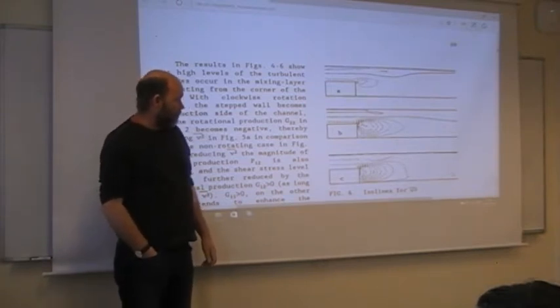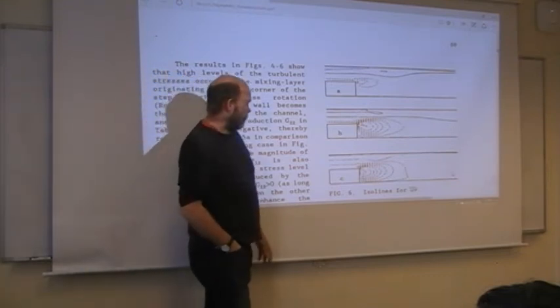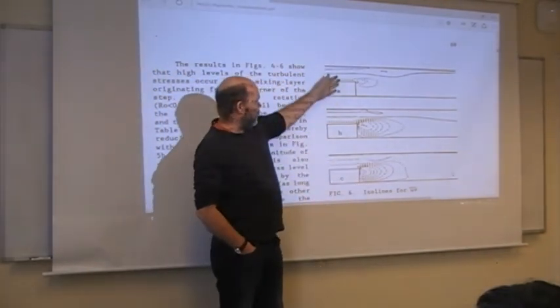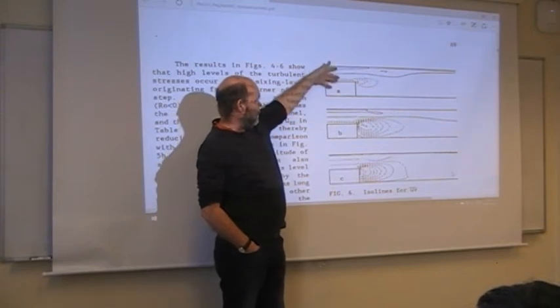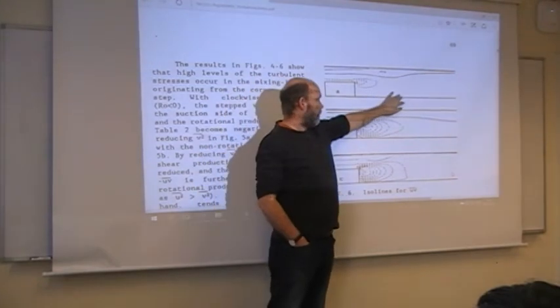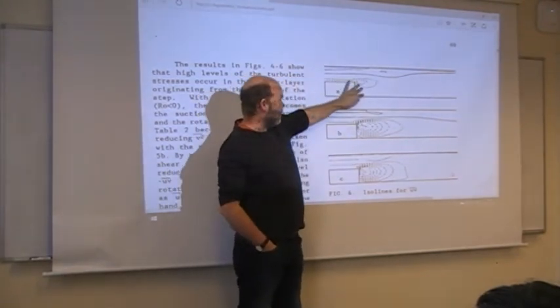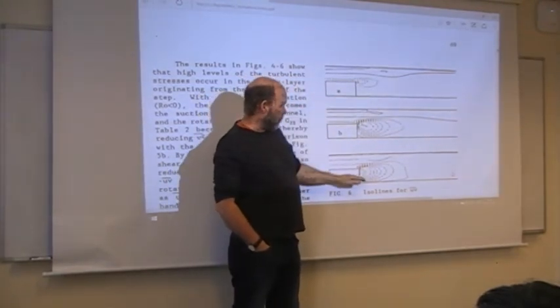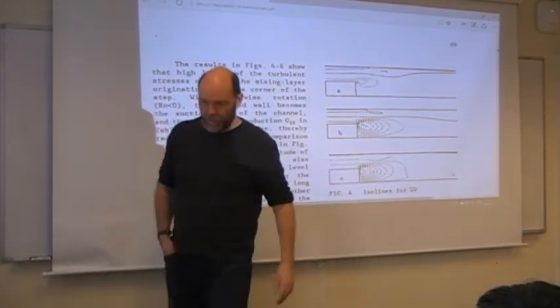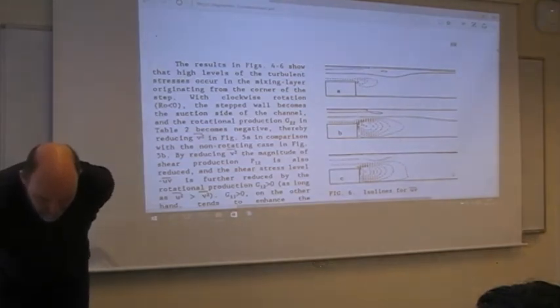The Reynolds shear stress, u-fluct v-fluct. Clearly some differences here, yes. The negative rotation softens it down, getting more and more laminar-like. Rotating in the positive direction, we increase the turbulent activity quite strongly.